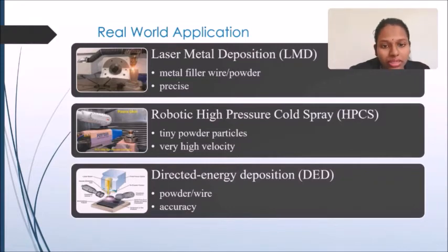And also the materials that can be used for this is titanium. You can use nickel, cobalt, and also steel alloys. They can be deposited onto a substrate to create a brand new surface. You can also use it to restore worn surfaces or to apply material to clad a specific area of a component. This LMD is computerized, meaning that all the movements and all the parameters are numerically controlled.